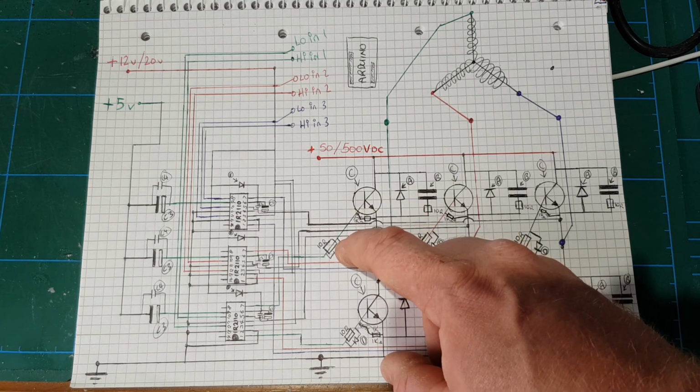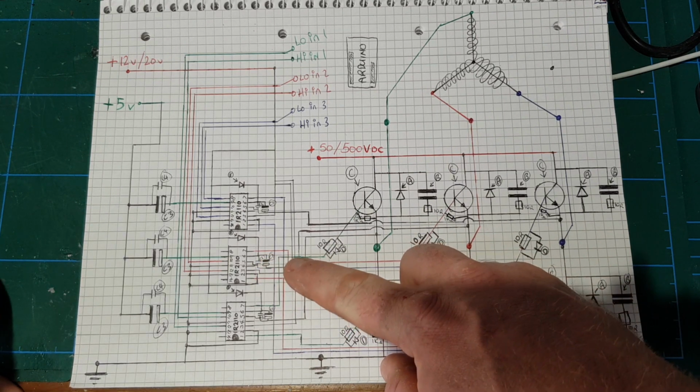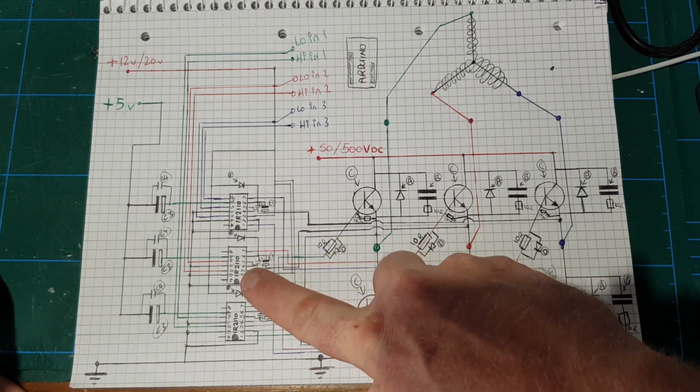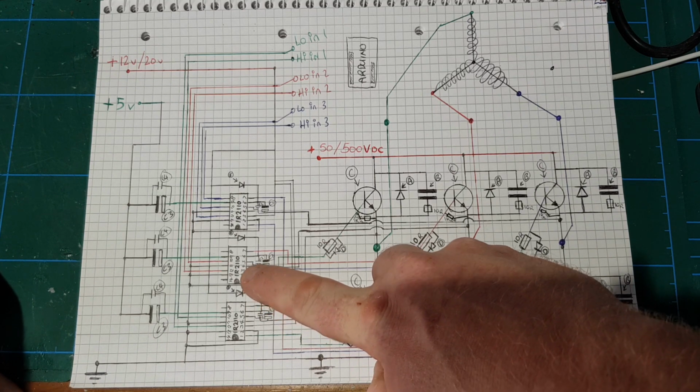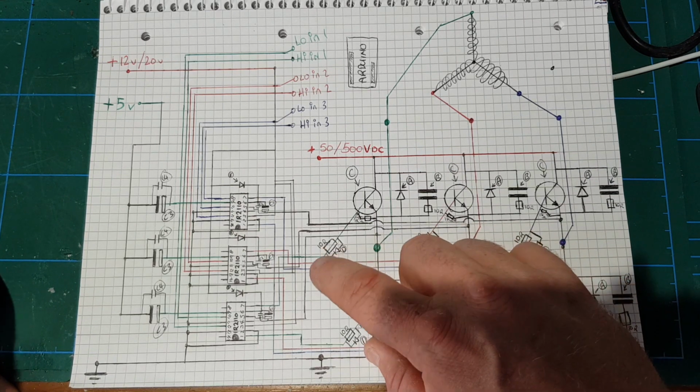If you get too much, you'll get ringing, and you could even blow the IR2110s up quite badly. They'll just short circuit. That's what these tend to do. Easy to diagnose because the chip just gets red hot. Stick your finger across them. Oh, that one's red hot. Look at that. So don't worry too much about that.